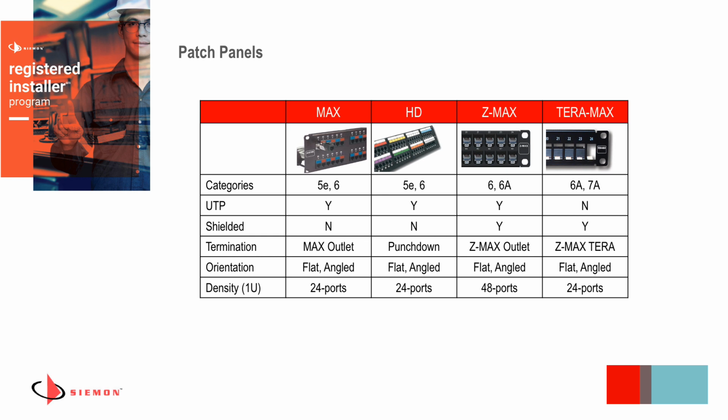So the MAX modules are designed for categories 5E and 6 UTP solutions. They're not available in shielded. Use the MAX outlet to terminate them. The panels are available in both flat and angled constructions, as are all the rest of them.